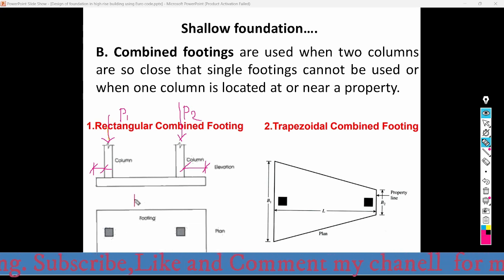This is for the case of a rectangular footing, that is, a rectangular combined footing. That means the magnitude of the column load P1 is approximately equal to the magnitude of P2. So in this case, it is recommended to use the rectangular footing or the square footing.